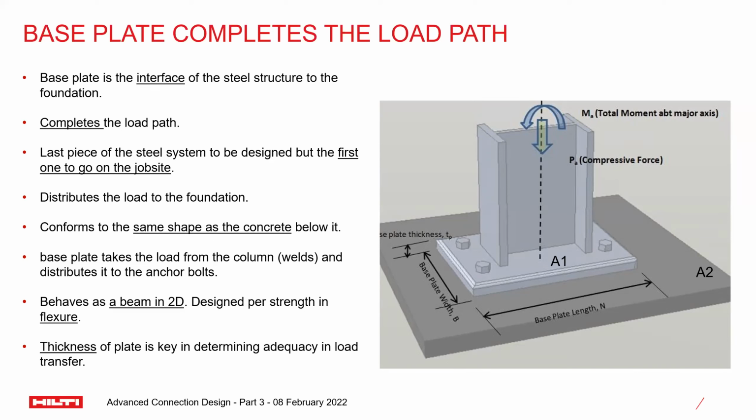So analysis of a base plate is very similar to beams. Think of base plates as beams in 3D. Like beams, base plates are also designed for their flexure capacity, and the design process is very similar. The thickness of the base plate is the most important design parameter, along with its length and width. We typically increase the thickness of base plates to avoid using stiffeners.